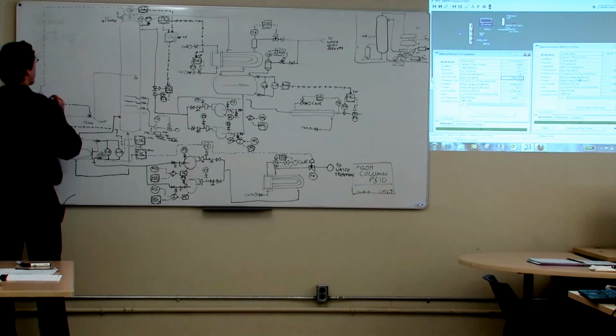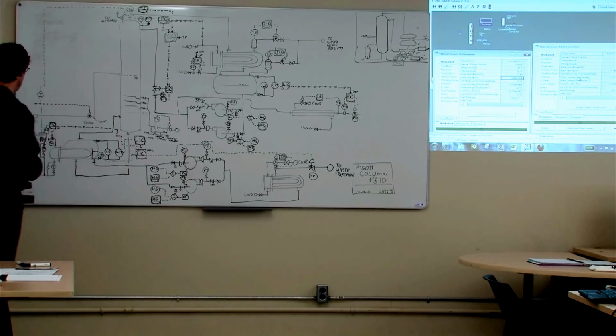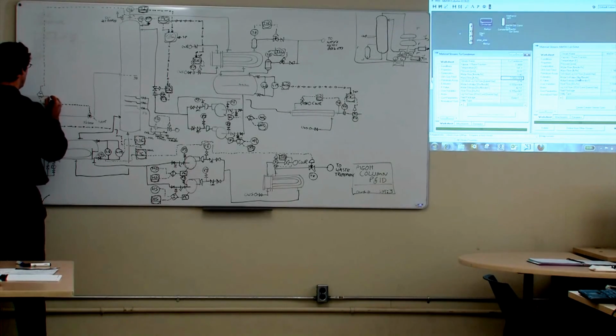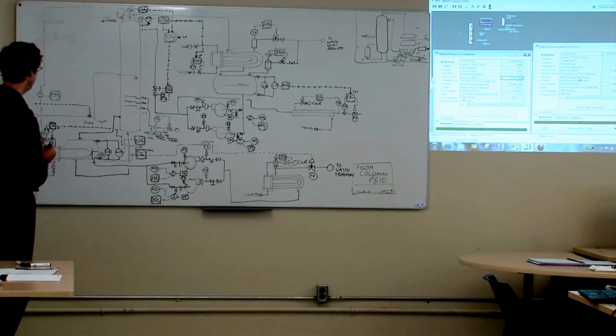Like that. Now, right now it's blind, and I can't tell that the pressure switch has tripped the reboiler. So I'm going to put a pressure alarm high in the DCS just so that I know something has gone wrong. So that's fixed the problem of the reboiler gone crazy.